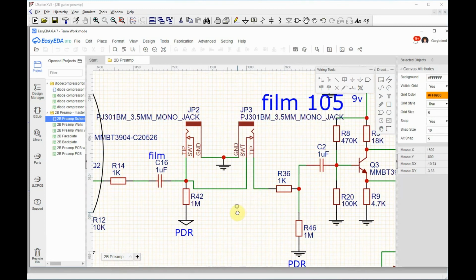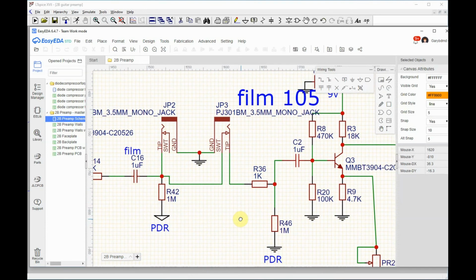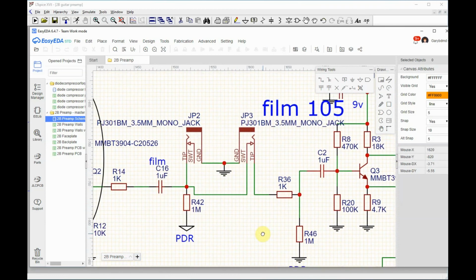You just have to think about unknowns, because you just don't know what you're going into. So you've got to plan for a big enough capacitor to make sure that's the case. You don't know the output impedance of what's going to be coming in through here, so you have to make sure you have enough input. I mean, you can just buffer each side if you want, but I found a lot of circuits don't do that. They just kind of figure you're on your own, but if you need a buffer, use an external buffer or something. But so I think that's probably enough on this.